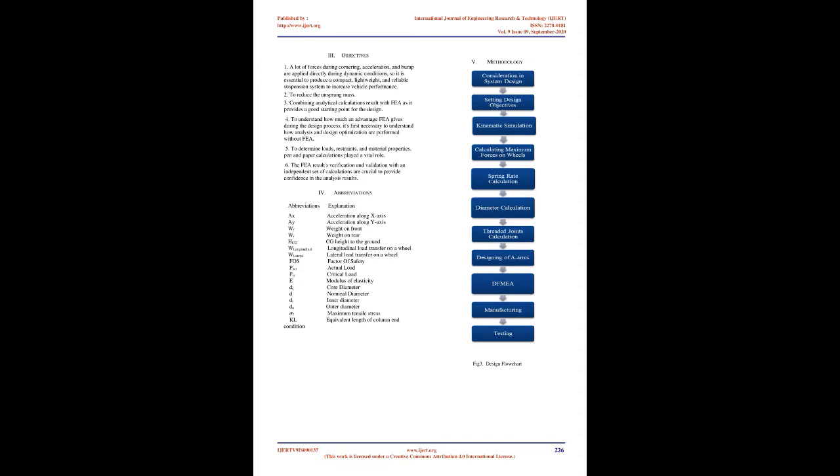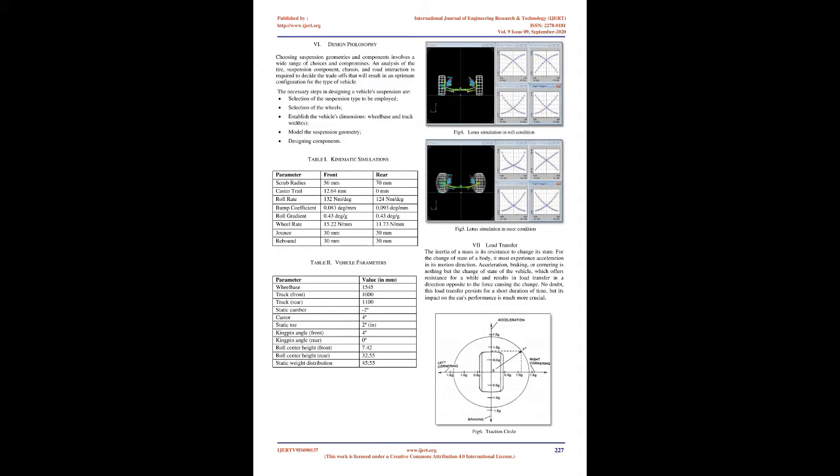As the double wishbone undergoes tension and compression forces, the yield and buckling need to be calculated, followed by the threaded joints calculation for the rod ends as the force is transmitted through these to the chassis. Double wishbone. 2. Problem statement. The double wishbone suspension system is independent. This design allows the race car engineers to control the wheel's motion throughout suspension travel, controlling the parameters such as camber angle, caster angle, toe, roll center height, and scrub radius.